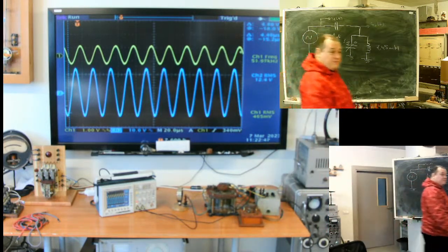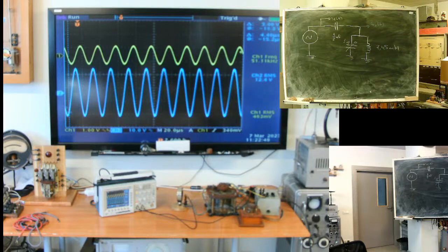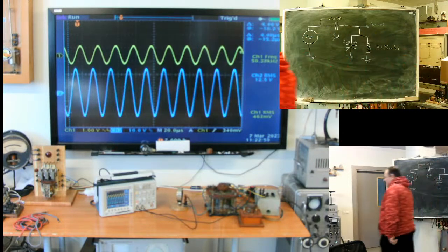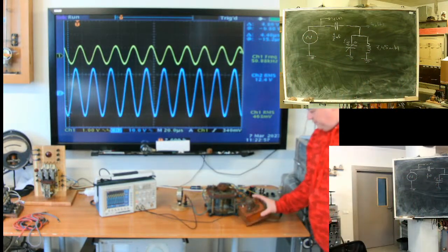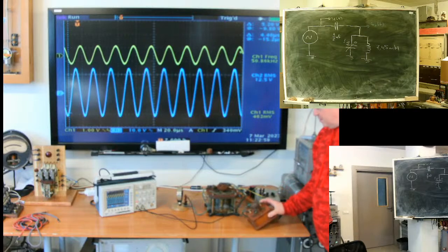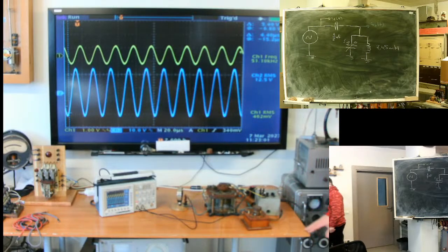Do we see something familiar? What's the difference between the adjustable capacitor and the normal? In capacitance, this one is fixed. I can show it without this capacitor. I just need to separate the network from the low output impedance of the generator. My generator has output impedance only 5 ohms at this moment.